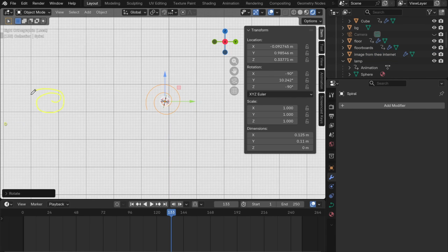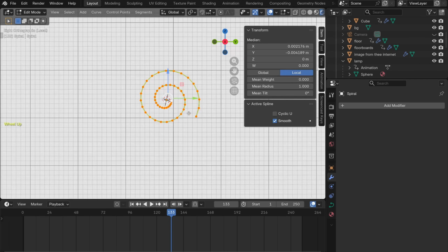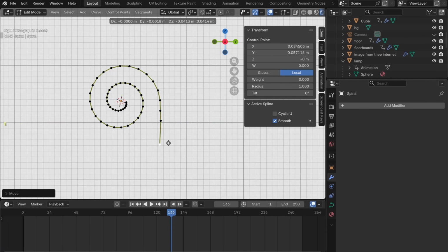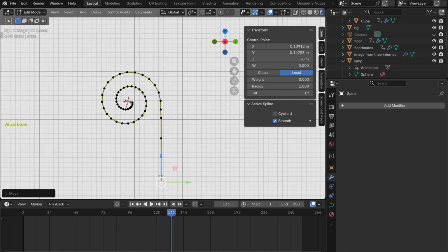But as you can see, the spiral is in the wrong direction. It needs to be on the right side, since that's where the wall is. So let's undo that. In the Y rotation, type -90. Now if we press R to rotate, it will give us what we need. Press Tab to enter edit mode. Select the endpoint. Then E to extrude. Z to lock the Z axis. Then left click. Exit edit mode.